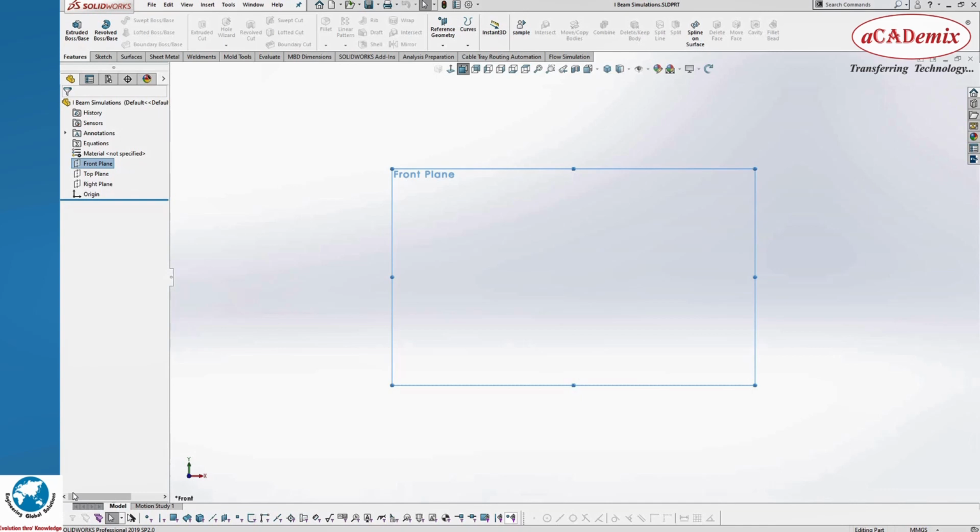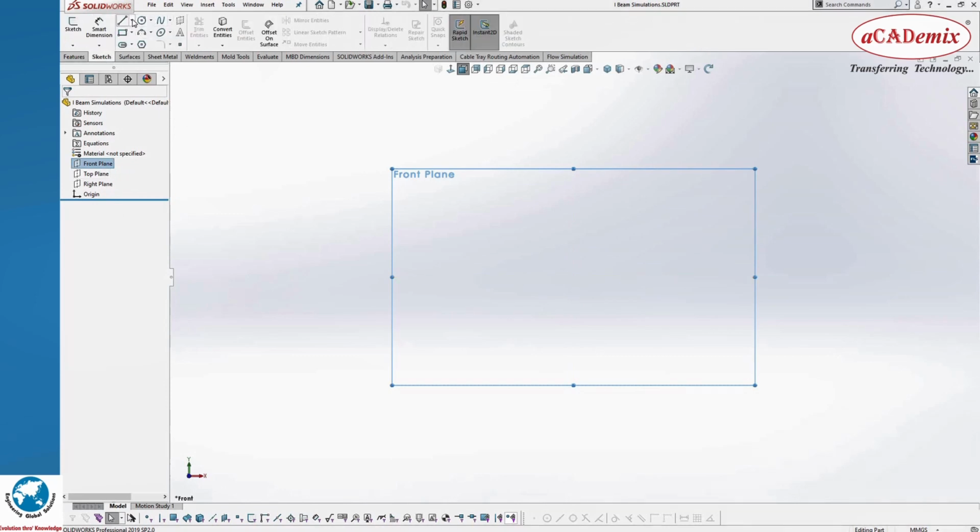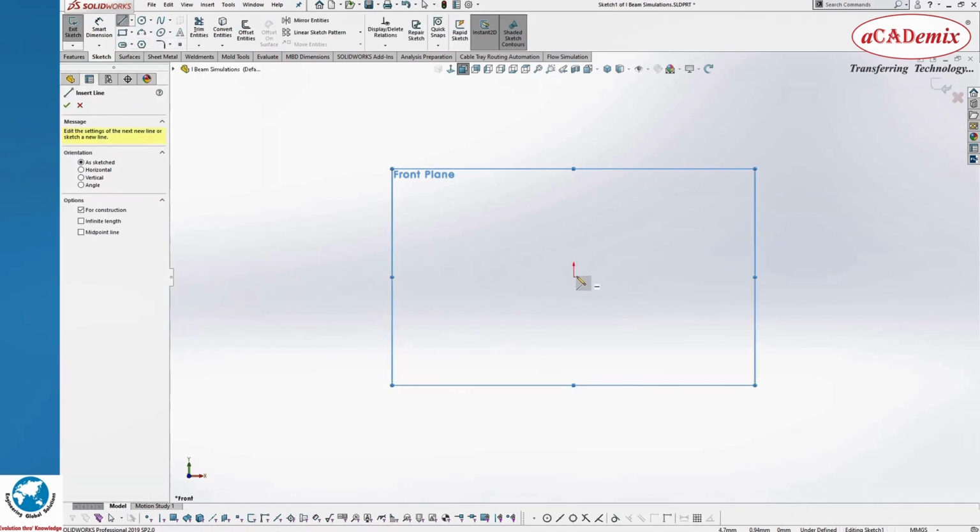The I-beam is an alloy steel universal beam with standard dimensions of 127 mm depth and 76 mm width. The thickness of the flange is 7.6 mm and web thickness is 4.2 mm. First, we are going to draw the I section in the Solidworks software. Now we have to select a plane, and now we are going to select the center line. First, we are going to draw it in the XY plane.